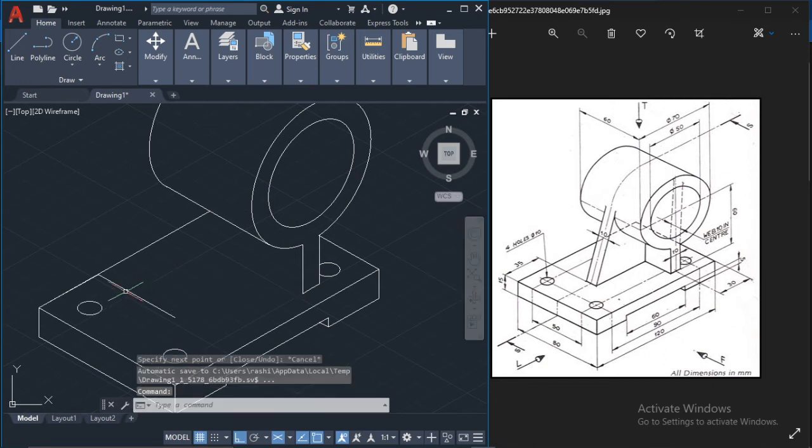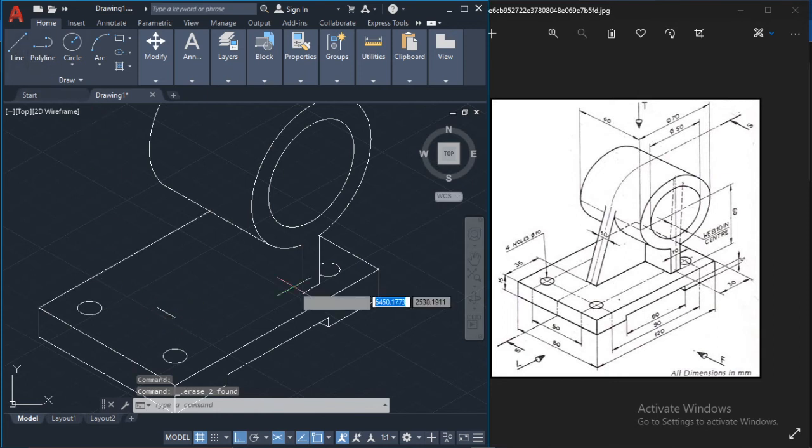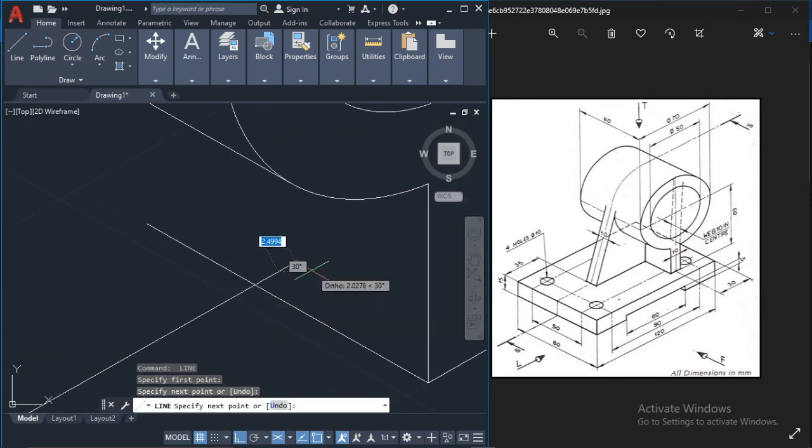There we go. So then we can delete these lines. We no longer need these lines. All right, so we have those. So then I can draw this line on the isoplane top. I'm just going to bring this across, no specific distance. And then bring this line back, again no specific distance, down here to where it meets that line. And then from here, I'm going to draw a line where these two lines meet. I'm going to draw a line up.